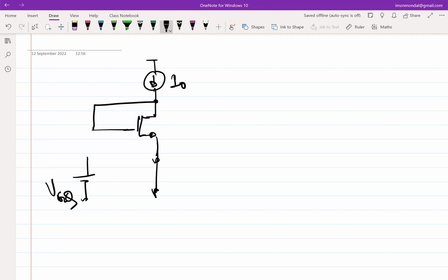I can change it by affecting the gate or affecting the source, right? So these are the two independent control terminals that I can tweak. Or in other words, if you have to bias your transistor using a current source, you use negative feedback, right? This example was that of a negative feedback.